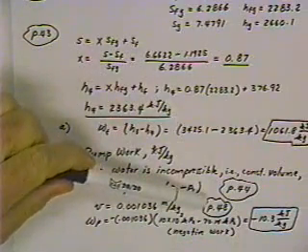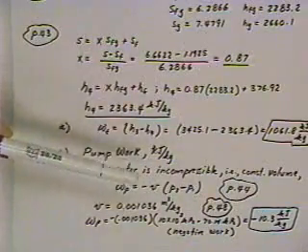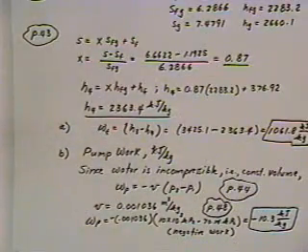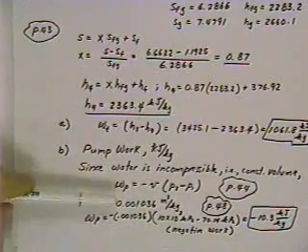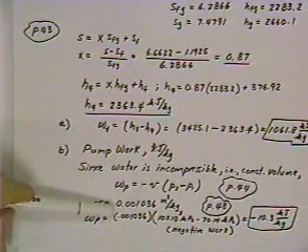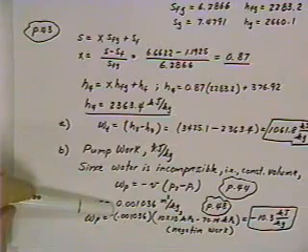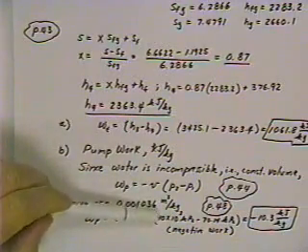Find from the tables on page 48 at the pressure of 70.14 kilopascals, V sub F. And so the pump work then is minus V, which is 0.001036, times delta P.